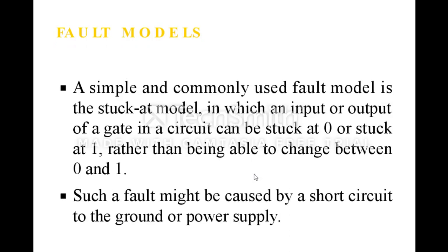A simple and commonly used fault model is the stuck-at model, in which an input or output of a gate in a circuit can be stuck at 0 or at 1 rather than being able to change between 0 and 1. Such a fault might be caused by a short circuit to the ground or power supply.